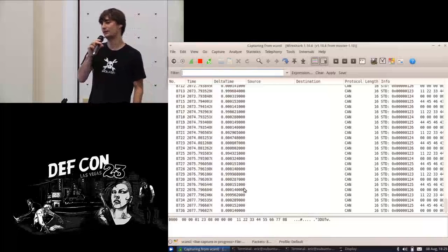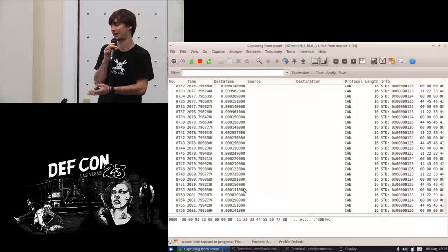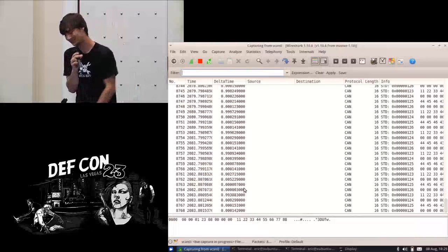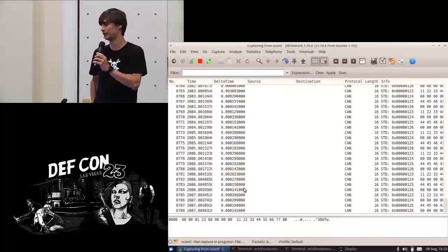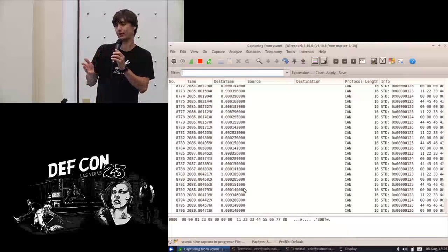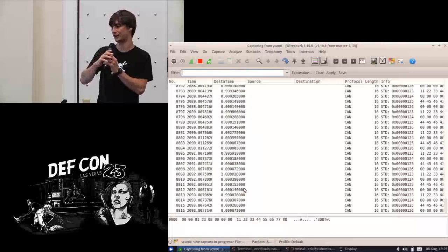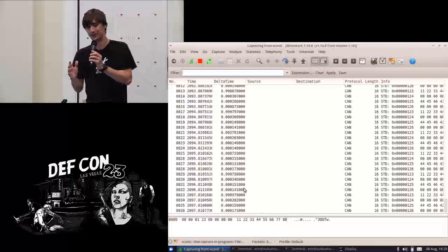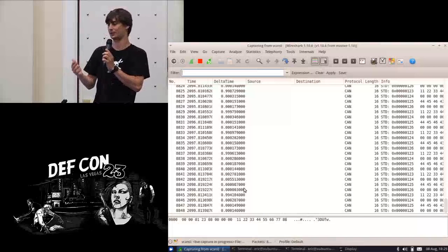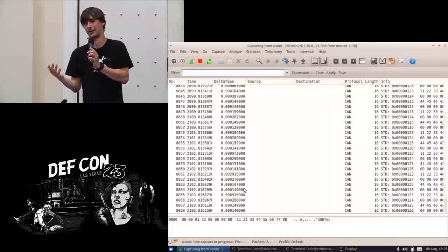Oh, okay. So if you want to figure out what ECUs are talking to each other, the question was, how do you figure out interactions between them? If you want to simulate an ECU, okay. So it's hard. CAN is a totally multi-master bus, and everything is sent to everybody. It's broadcast. So every message that's sent out could be received by every controller for all you know, and you have no idea really how they act.